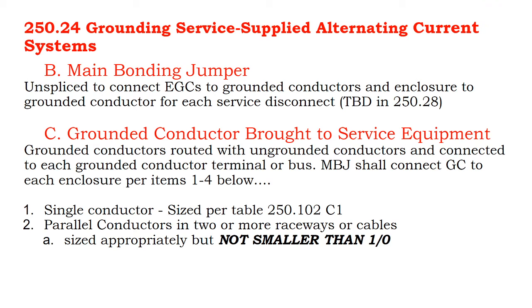You're allowed to design some equipment with small parallel runs and then go get it UL listed and provide an assembly, and everything inside that listed assembly, you have that UL listing for. You're not allowed to design un-UL listed systems of your own design and do parallel conductors for ampacity sizing for anything smaller than 1/0.